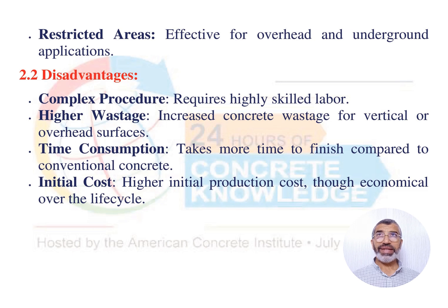requires highly skilled labor, especially for the dry mix process, which we'll explain later. Also, there is a higher wastage in the shotcrete process compared to conventional concrete casting because of the rebound amounts of concrete wasted, especially for the vertical and overhead surfaces shotcreted.